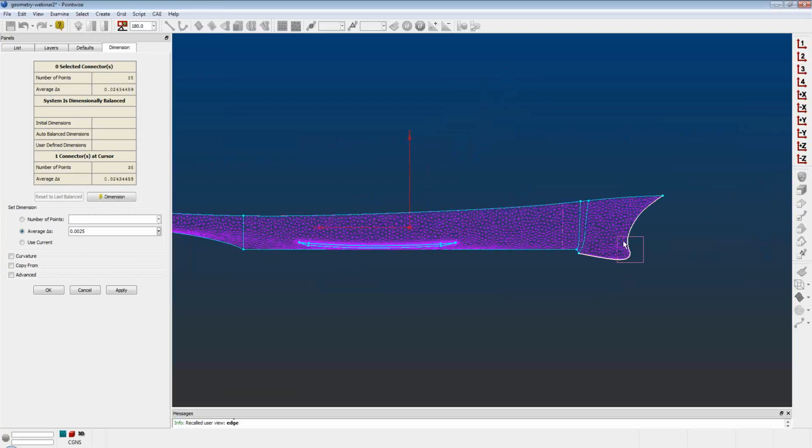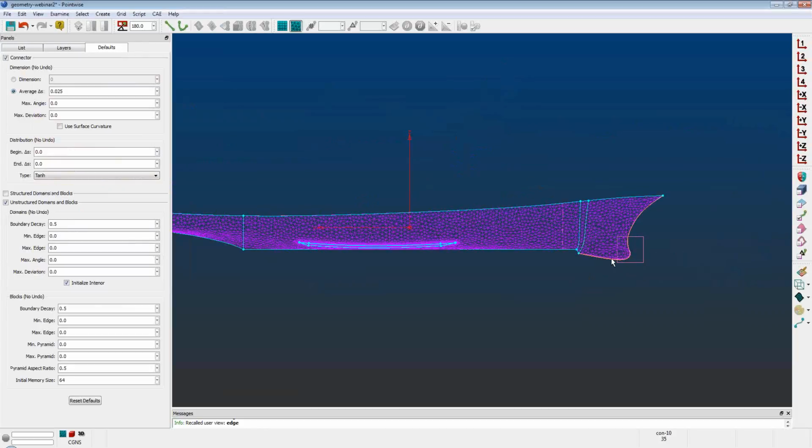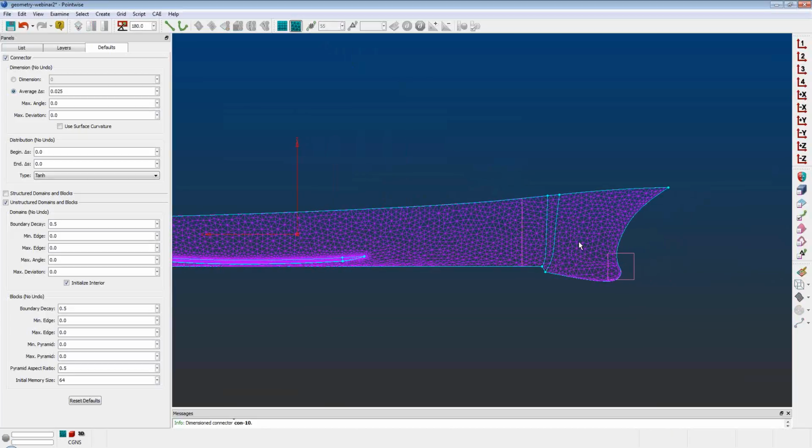And yeah, like again, I can even just show, I'll get out of this panel, and it's telling me right now I'm hovering over the curve on the bow of the hull, and at the very bottom, it tells me there's 35 points in that grid curve. So I'm just going to go and say I want 55 grid points, and it will automatically do that, and it will refine the mesh as you need it. So there's a variety of tools built in for doing that. And if you have some more questions about that, send me an email, and I can give you some more examples or try to clarify that for you. Thank you so much. No problem.